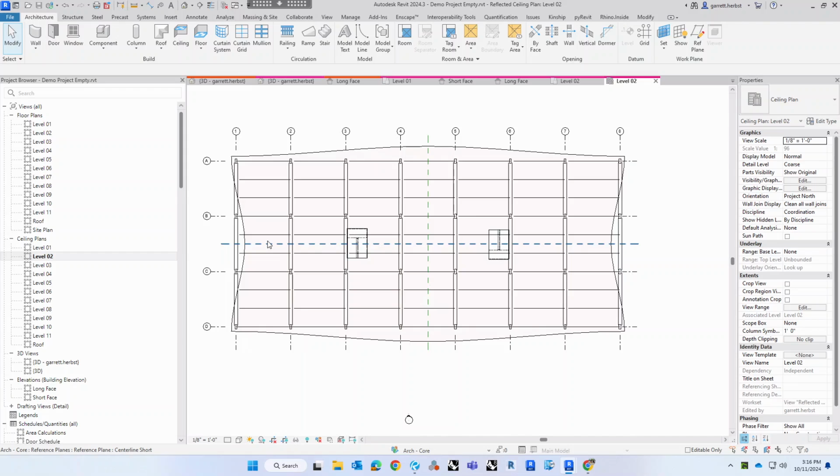I'm just going to draw it out of walls because of time. Now, of course, if you want, you can create a CLT. Do I have that in here? I might not have it in here. Oh, yeah, I do. You can create a CLT shear wall out of the basic wall component. Now, you're not going to be able to figure out the fabrication of them. It's not as technically specific as actually drawing the panel width and locating them all. But it's a good way to quickly generate that.